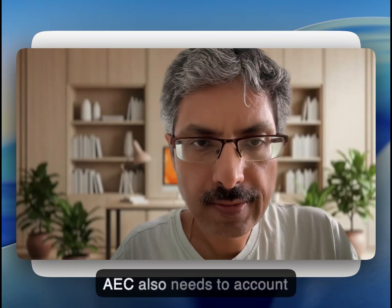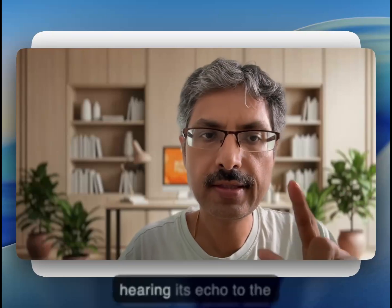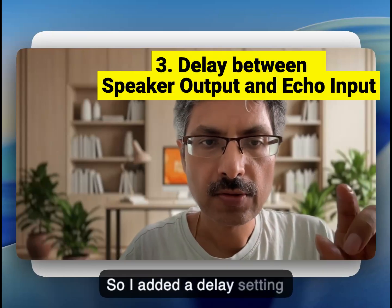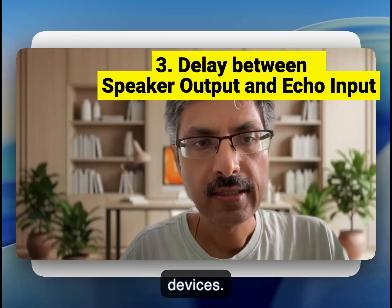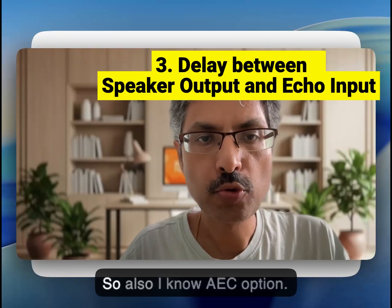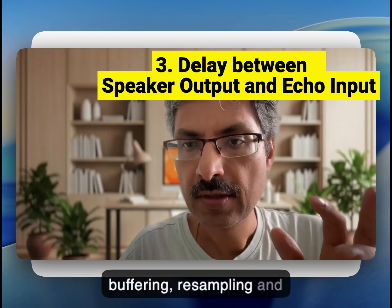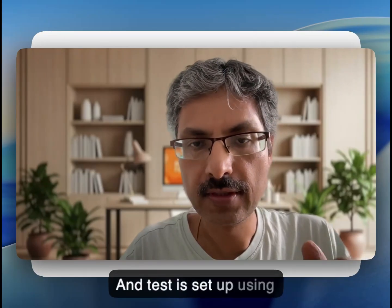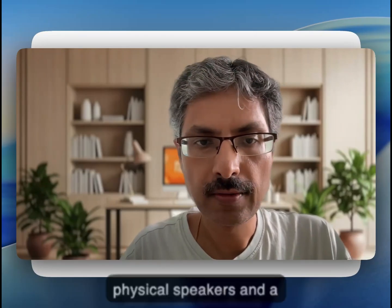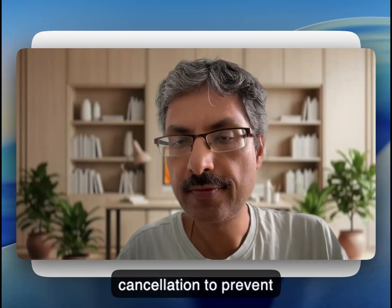Another hurdle, AEC also needs to account for the small delay between playing the audio and hearing its echo at the microphone. So I added a delay setting that can be tuned for different microphones, speakers and audio devices. Default is 40 milliseconds. There's also a no AEC option. Finally, I added tests for buffering, resampling, and interruption handling, and tested the setup using physical speakers and a mic on my MacBook.